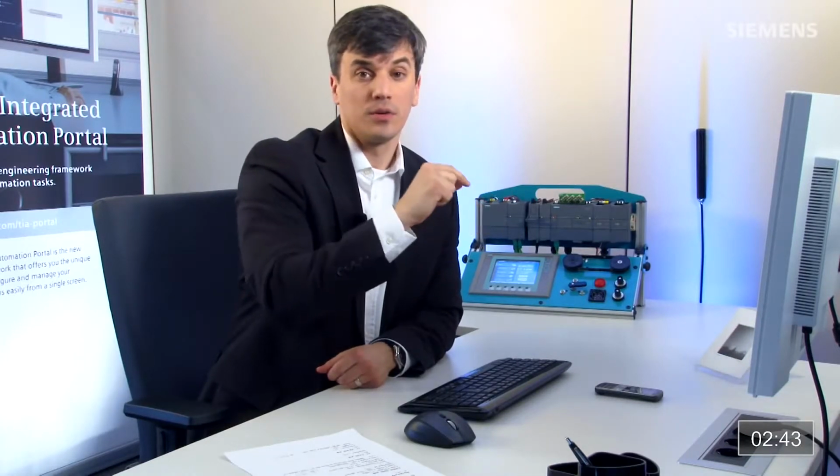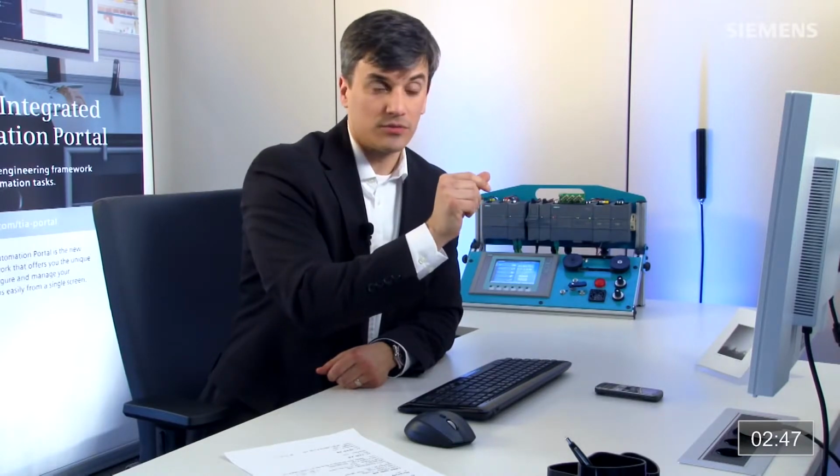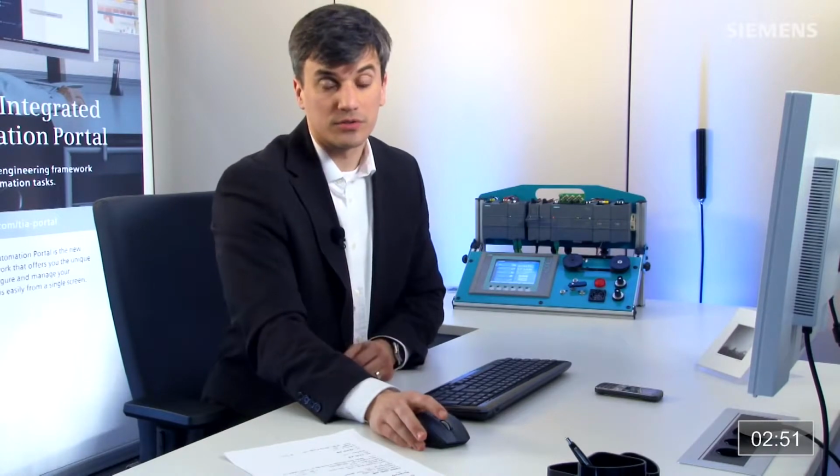So the next step is we want to give focus to the PLC and click the download button. Ultimately, if you think about what we've been able to do, we were able to scan the Profinet network, find this physical hardware, including this new GPRS module with all the other signal modules, and all we had to do was change the attributes and click on the download, and we have a fully functional system on the cellular network at the same time.